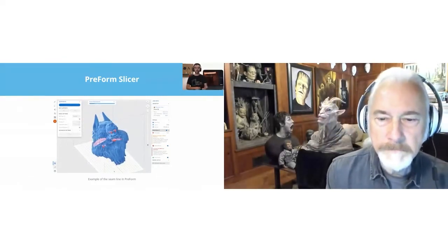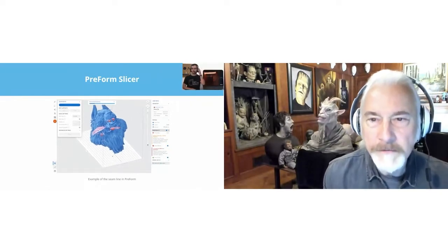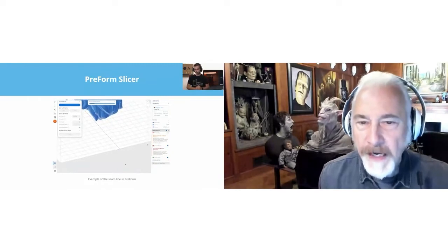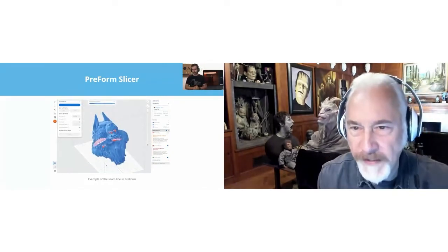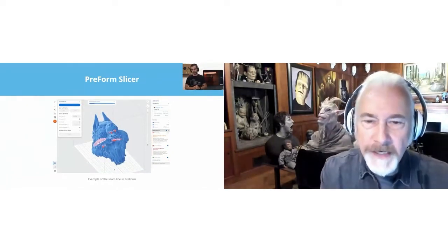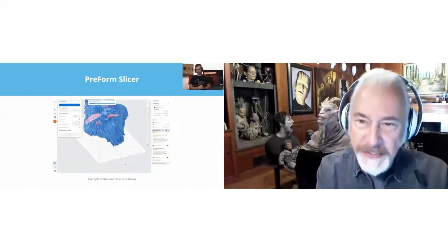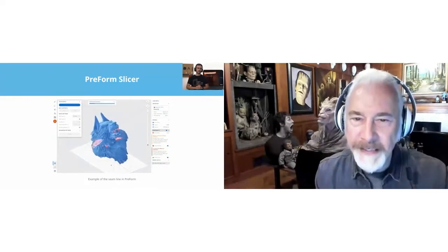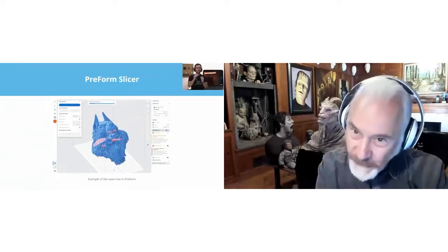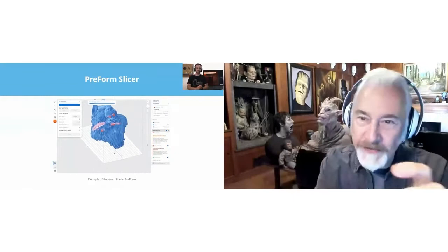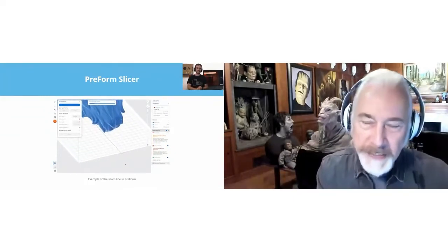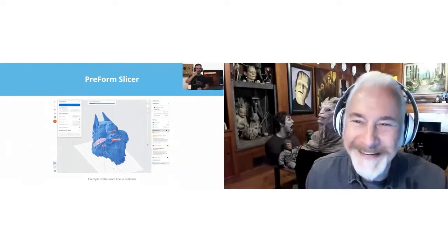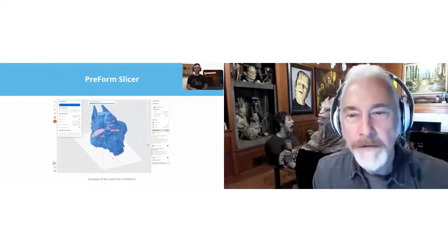And if you need to, you can go in and do it manually, which is what I do. Yeah, I'll do the auto-generated supports, but it also shows that there's cupping or whatever. It says they can blow out, which is a little annoying. I thought I positioned this piece a certain way, and then I put it in PreForm, and it tells me that I'm going to have a cup there. So I'll reposition it and change it around and try different supports, and eventually it says, okay, it's good. Gives you a thumbs up. So yeah, you want all those green lights, all those green thumbs ups.